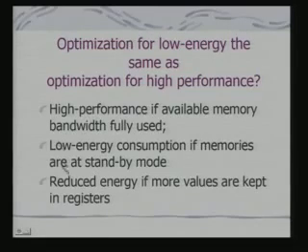So if I look at this possibility, if we are keeping the variables in registers, what happens? The instructions involving registers may consume less energy. If it is consuming less energy, then it is becoming power efficient, and in a way it will consume less energy because there is no activity on the bus.